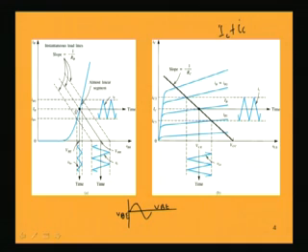When IC is minimum, then we will get VCE maximum. Now, for a particular value of resistance in the collector, we can draw the load line. If we want to draw this DC load line, we join the maximum points on the voltage as well as the current axis. The maximum point of the voltage is obviously VCC, when you have 0 current in the collector.